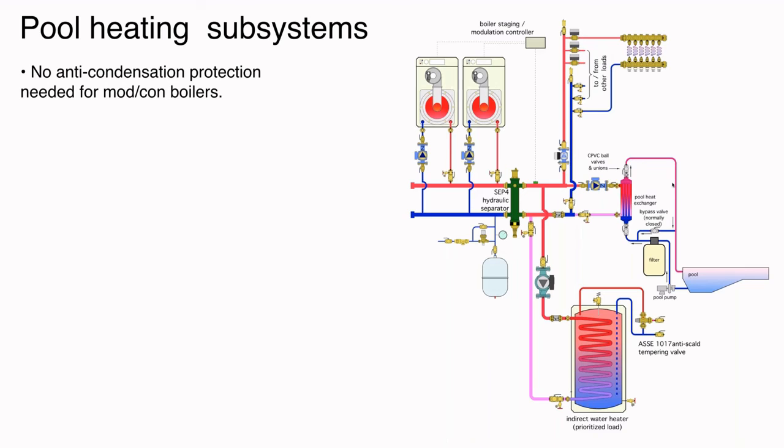It's basically going to suck up BTUs wherever it can, and the result of that is going to pull the whole system temperature down. So you need controls, again, that would prioritize your other loads. I like to think of a pool heating load as a load that you can do almost anytime within a 24-hour period, as the lowest priority in the system.